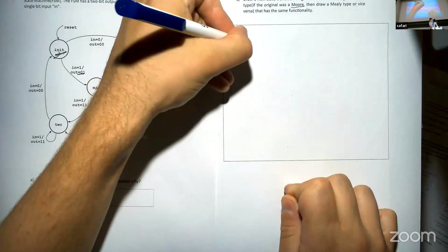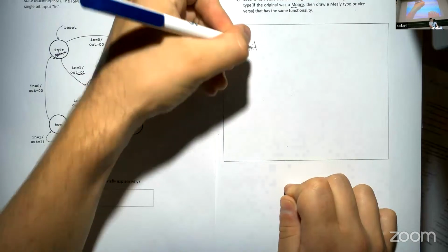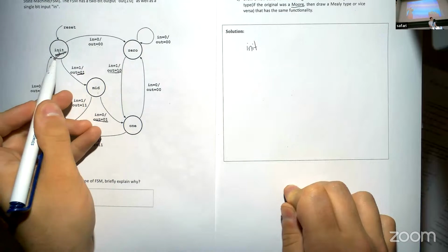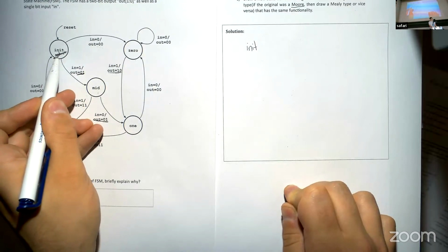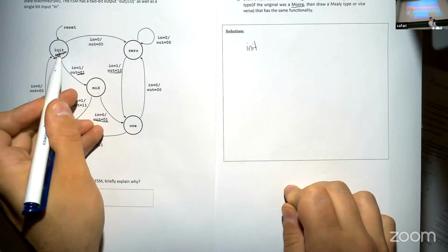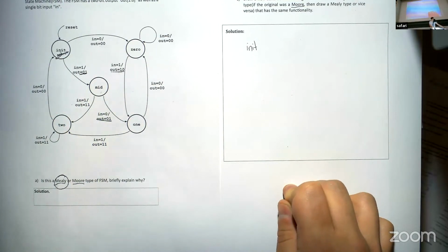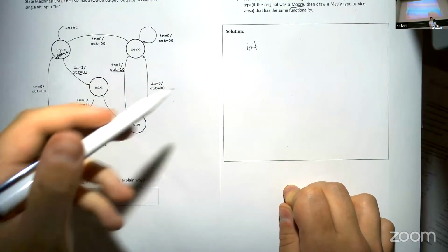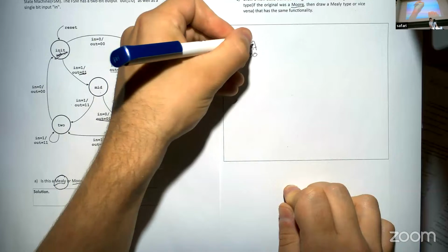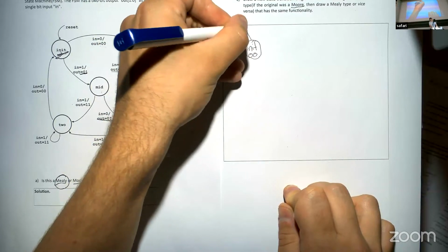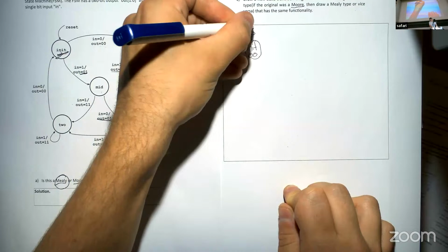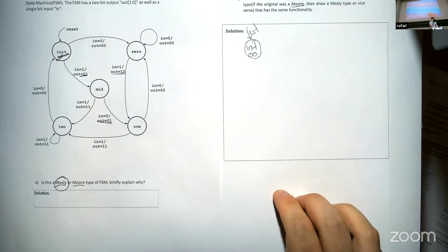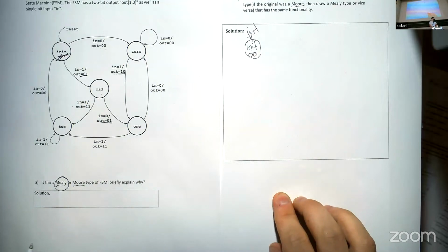So we take the same state and we just add to the name of the state its output on its ingoing edges. The init state has only 1 ingoing edge with the output 0, 0. So we call this state init 0, 0. Never forget the reset signal that always costs points, and it's so disappointing in the end. Also when correcting these exercises.